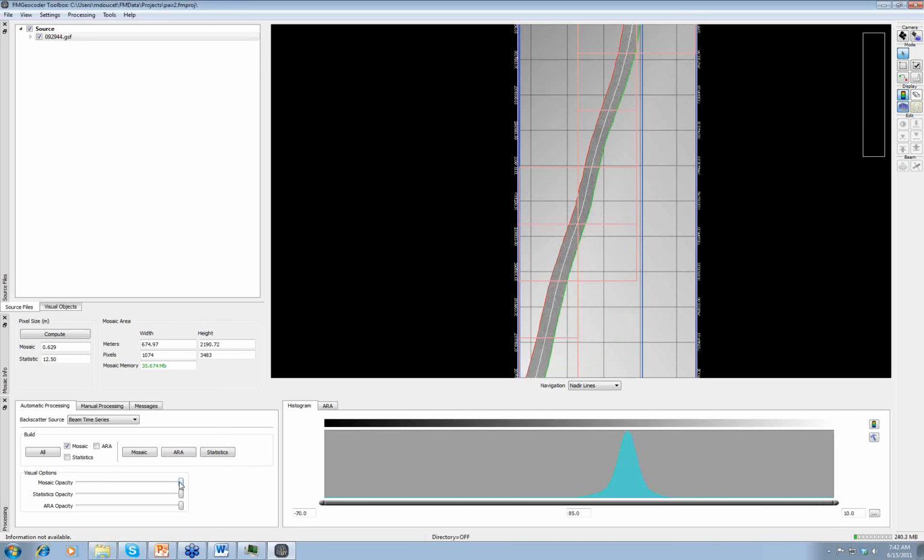And then when GT completes processing, and in the case of that data set, it was over 5 gigabytes of tiled imagery, GT will try to load as many tiles as it can if it's 32-bit and just say, hey, I couldn't load 15 of the 30 tiles, and just present to you what you have. But you can still get the data processing done. Now, of course, the way to get around that is to just use the 64-bit version.